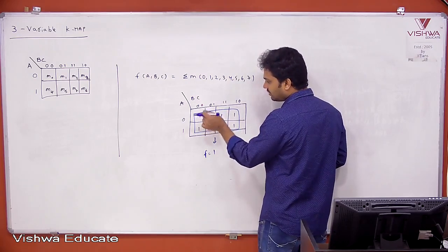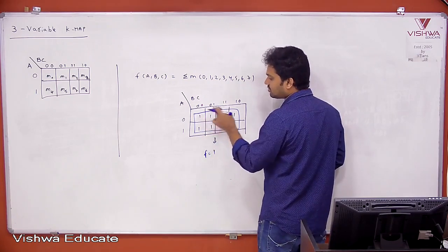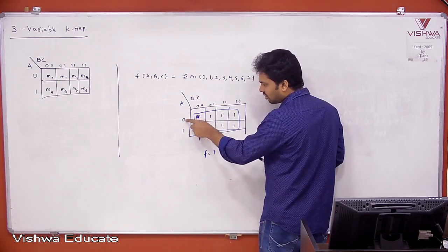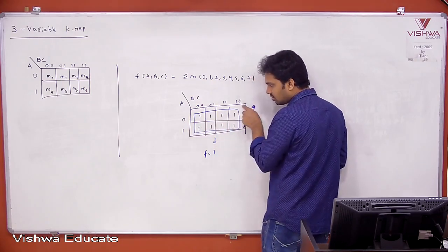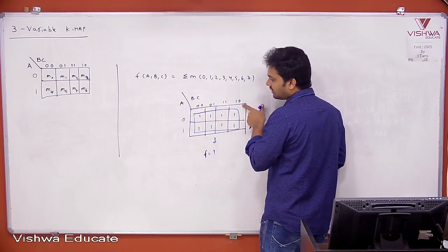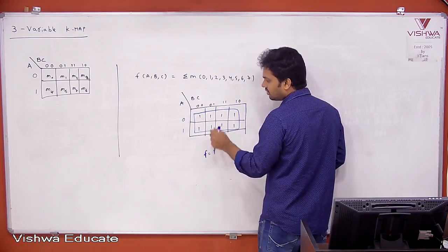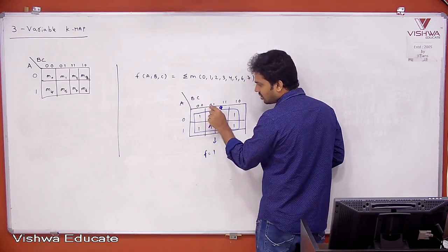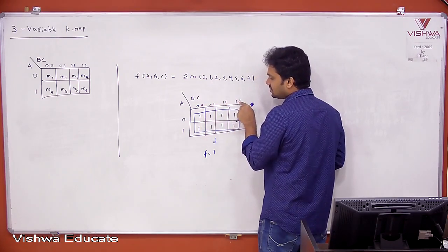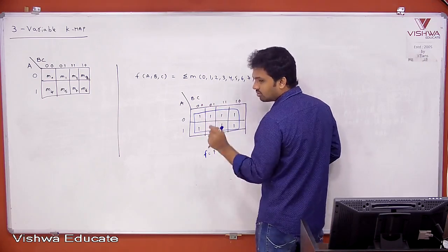But our ultimate answer will be same, and I told you already, whenever octet is possible, go for octet, go for maximum possibility only. Don't confuse, here nothing is common, in this row also nothing is common in all the terms, so you can neglect all the terms. Or if you add all this, you will get 1, you add all this, you will get 1. Adding means like this, B bar is common, C bar plus C is 1, B is common, C bar plus C is 1, B bar plus B is again 1, so 1 into 1 is equal to 1.